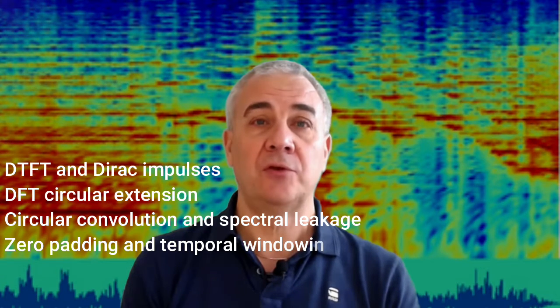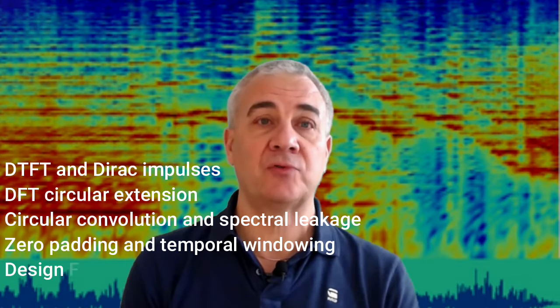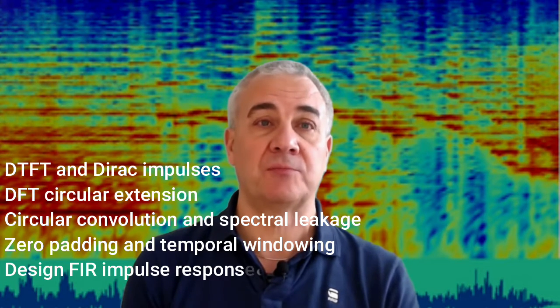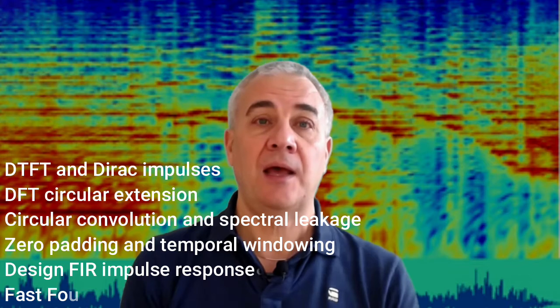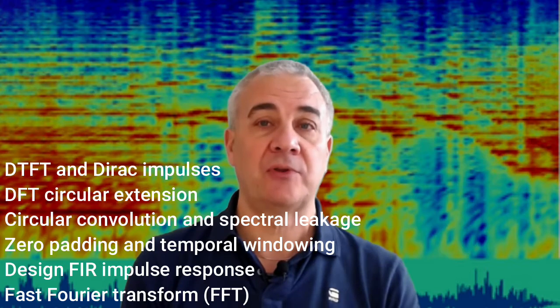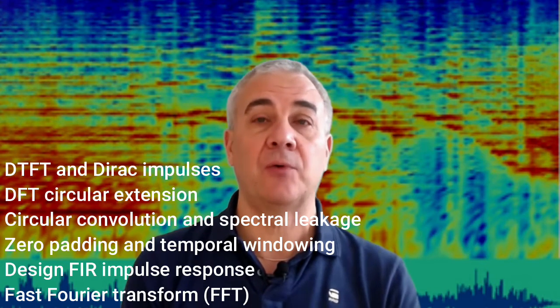And then fifth, the use and trade-offs in designing the impulse response of FIR filters, starting from the desired frequency response. And finally, how the DFT can be efficiently implemented as a FFT, Fast Fourier Transform, by exploiting the structure of the DFT equations. Let me start with a peculiarity of DTFTs when dealing with discrete time signals that contain harmonics, that is, pure sinusoidal signals.